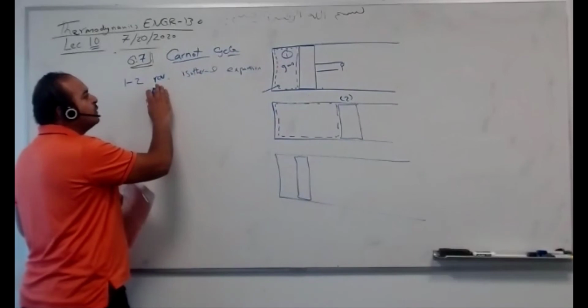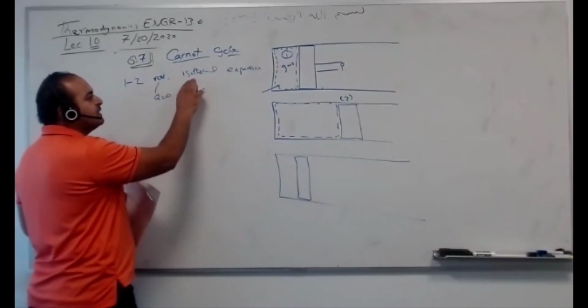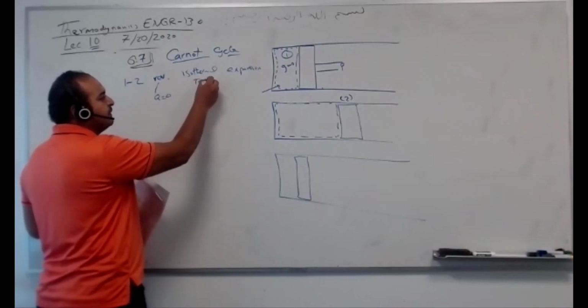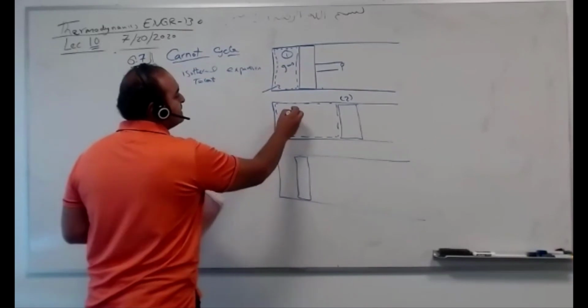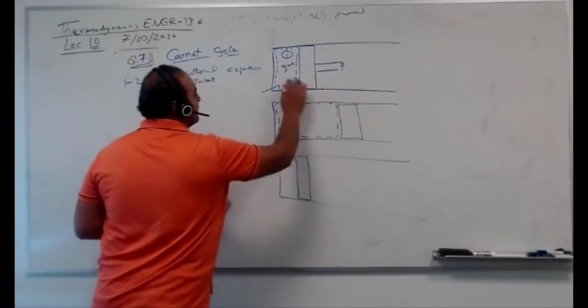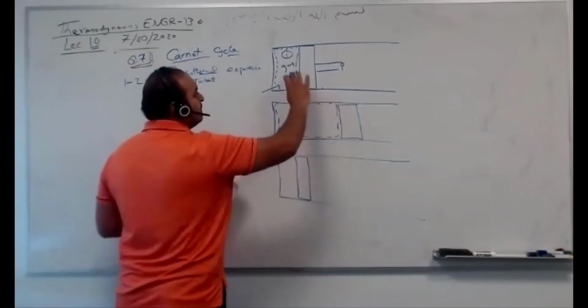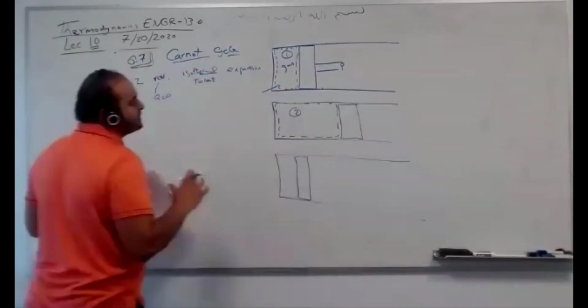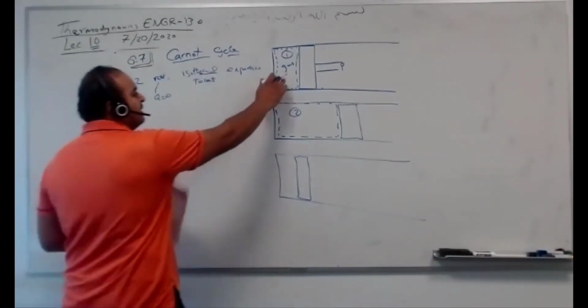Reversibly, there is no heat added. Reversible, Q is 0. Isothermal, temperature is constant. Temperature starts at 50 degrees, remains 50 degrees. This is state 2. State 2, temperature is the same as here, isothermal. Expansion, the pressure here is smaller because it expanded. Volume became bigger, pressure dropped. Here it was what, atmosphere? Half atmosphere.